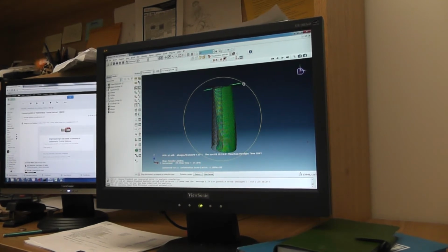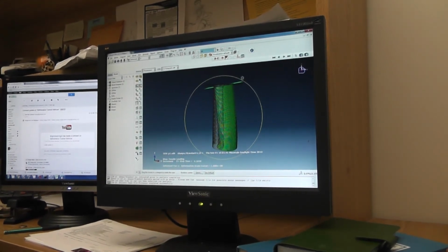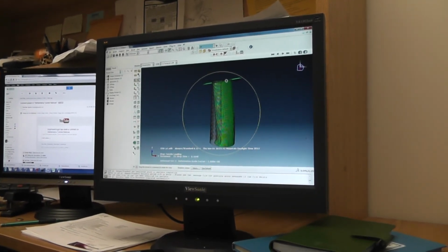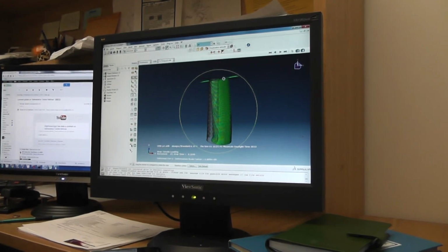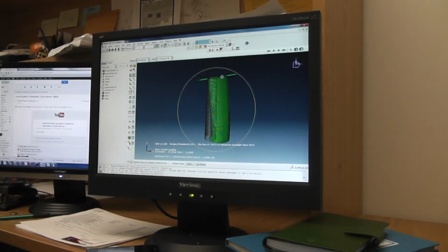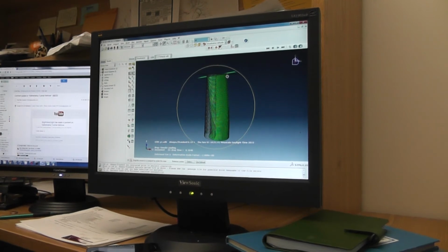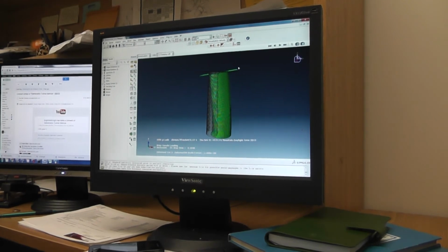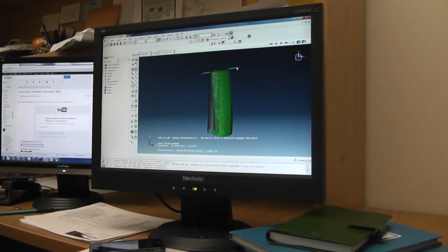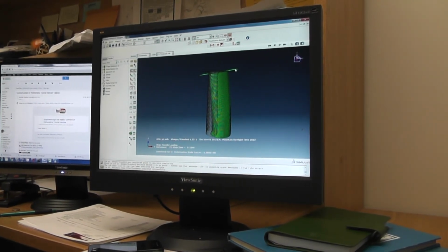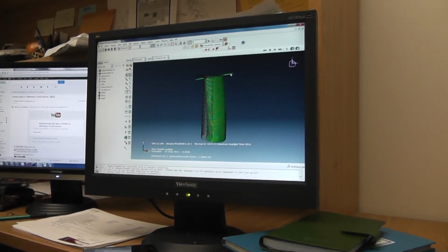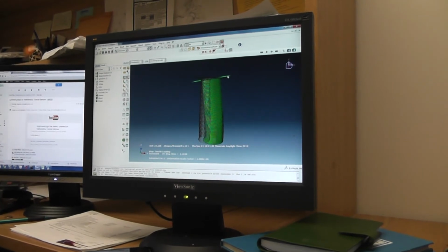This is compression because I used a very small area where I applied the load. If I use a bigger area to apply the displacement, it might not rotate that much. See that huge rotation? Because I just picked a knife edge, basically. I picked the knife and pulled on the plate. But we need to understand how we can pull on that plate and let it rotate but not so much.